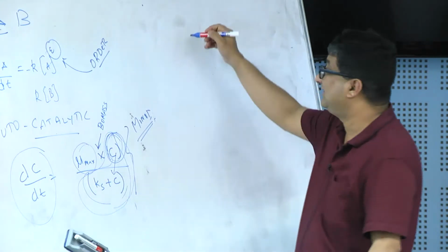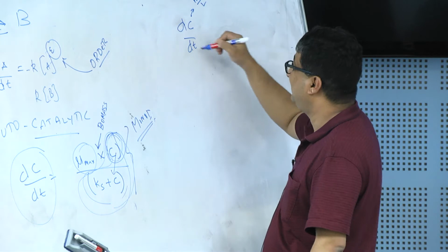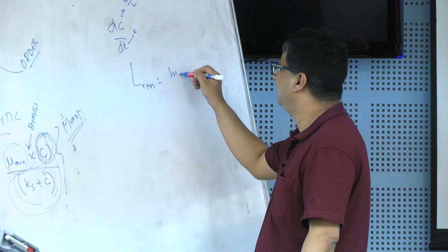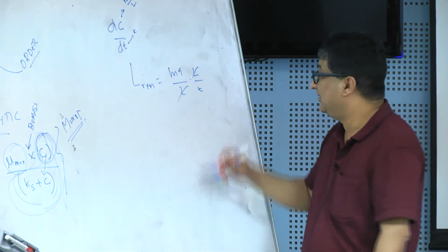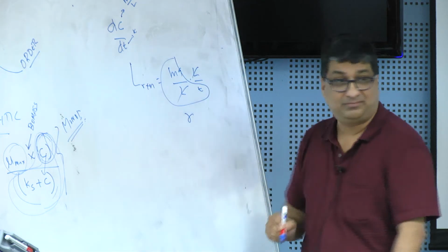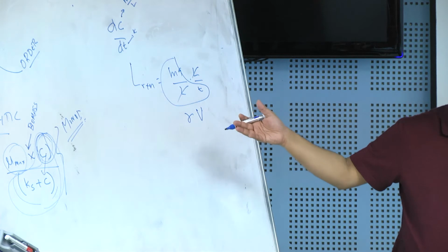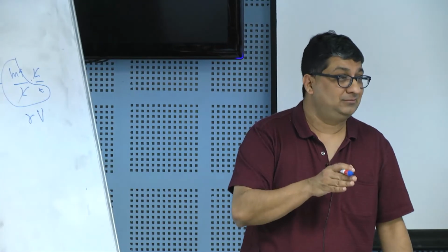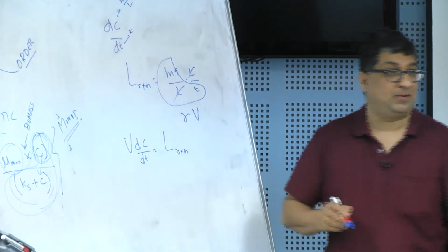So we know there is something called a reaction rate, dC/dt. This is milligrams per liter, and this is time. If I want to get a loading term, I'll get milligrams per time, or mass per time. So if I multiply the rate term times the volume, which will be my control volume, I will get my reactor rate. That is my loading due to reaction.